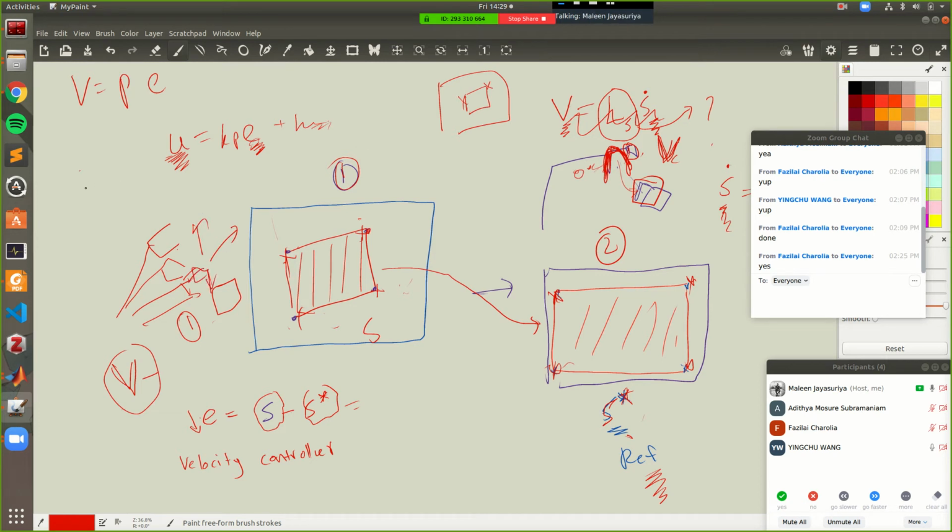You can control the velocity of the gripper in the x direction, y direction, z direction. You can control its rotations and all that stuff. But the relationship between this and the error is not a direct proportional relationship like this. Just because you multiply this error by a proportional value and equate it to the velocity, it won't go to where you want it to. It will just increase the velocity in different directions. So we need to intimately understand how the error in these features is directly related to each of these components of the velocities. Does that make sense?